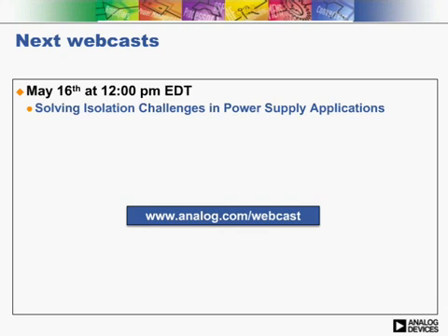Another great question. This was done to accommodate not only various converter resolutions and speeds, but also the migration of process technologies to faster speeds. As converter technologies are evolving, process geometries are getting smaller, and so current technology is just beginning to push the envelope of these higher speeds. So the speed grades are a way to allow the technology to catch up and be able to accommodate the faster data rates, and also help future-proof the specification and allow it to be scalable to meet increased converter resolutions and speeds.